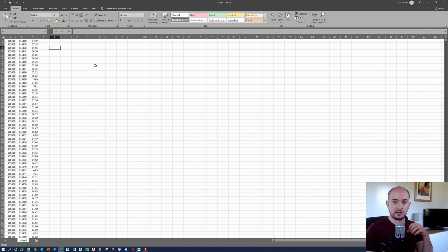And you'll see later on in the video in Civil 3D, I can actually define the type of delimiting or spacing requirements that I want the software to read. So in this instance, .csv is my recommendation, and it generally is my recommendation because it seems to carry through all the programs. So Revit recognizes .csv points, CAD recognizes .csv, Civil 3D recognizes .csv, and so on. So export as or save as a .csv format, okay?